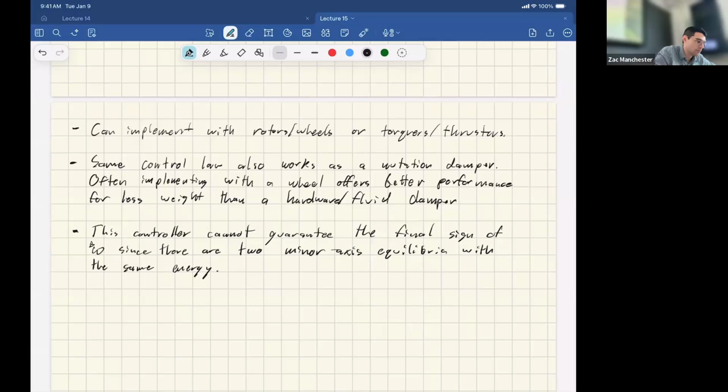How do I decide what the U's should be to produce a desired tau? So maybe I'll draw it cartoony, vector style. Tau is 3D, say. So this is like a 3D thing. And then in general, B is big and fat, and U is much bigger than tau. So if I tell you I want a certain tau applied torque on the spacecraft, how do I back that into a U that I apply to the actual actuators? Thoughts, ideas?